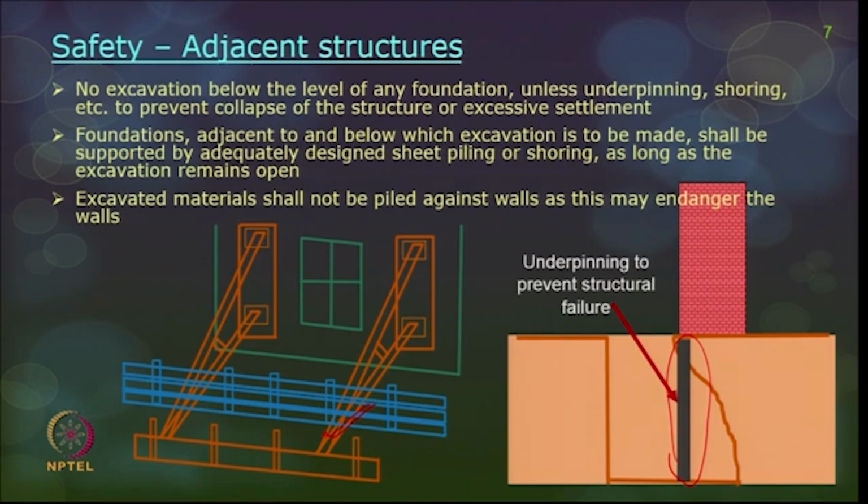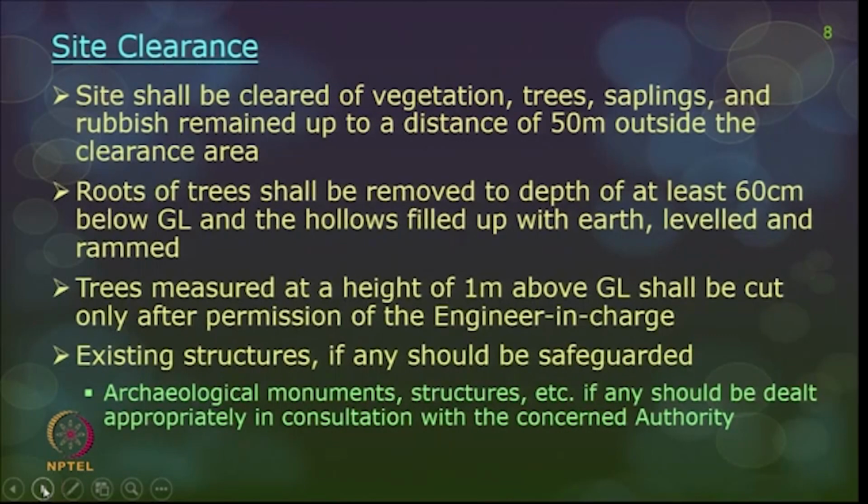The foundations adjacent to and below which the excavation is to be made shall be supported by adequately designed sheet piling, shoring or any other agreed method until the excavation of this particular site is open. And the excavated materials also should not be piled against the walls of the neighboring structures, because those buildings can collapse, so you have to take care of that.